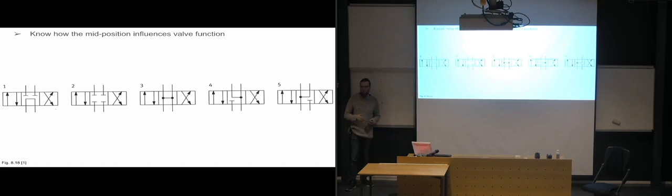The only resistance that we're getting is when it's pushing the fluid through the filters. So depending on how much of a pressure differential we have going through the filters, we're going to have a little bit of pressure, most likely a couple of bars or something as it's moving the liquid around, but nothing like an operating pressure of 220 bars or anything like that.